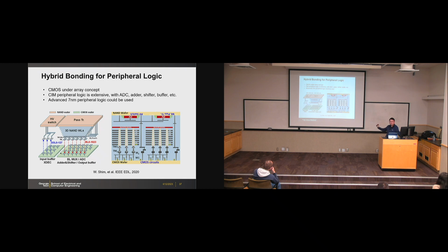from the industry nowadays. For example, TSMC has this so-called SoIC, face-to-face hybrid bonding with a bonding pitch of a few micrometers. So in principle, we can have many paths between two dies, and then do the face-to-face bonding. Therefore, we can have a 3D NAND process and also the logic process in separate technology nodes. Then we can do the integration in the future. So this is just a proposal.